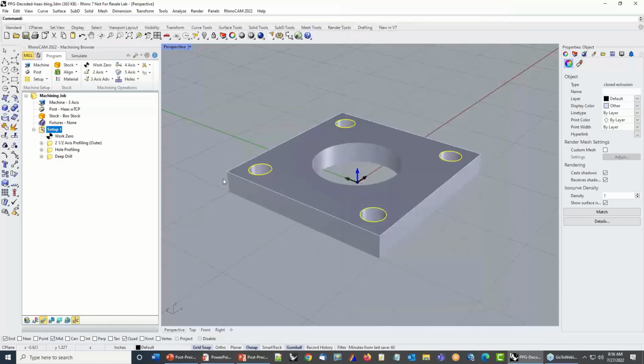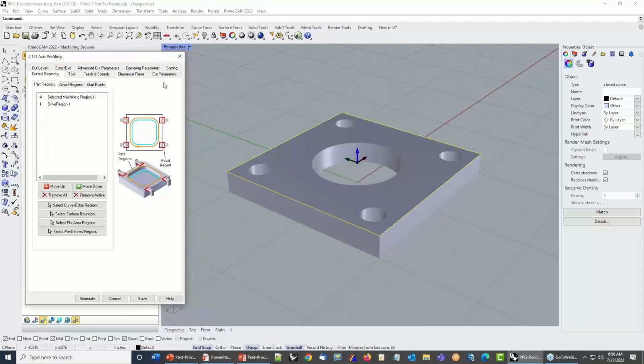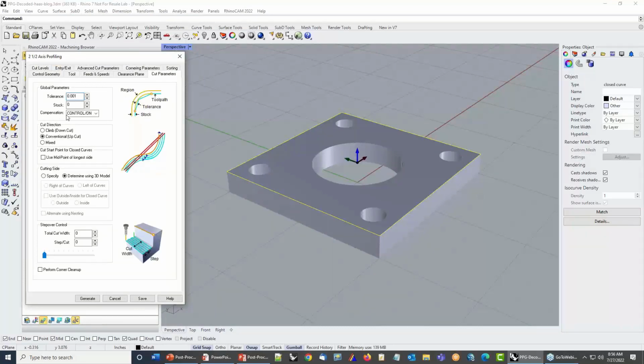Okay, let's move on. Cutter compensation. I'm just going to show you the different things that we covered. You want to make sure that you have linear motions defined. Initially, obviously, turn on compensation in your operation dialog. Make sure that's set to control on or auto on.